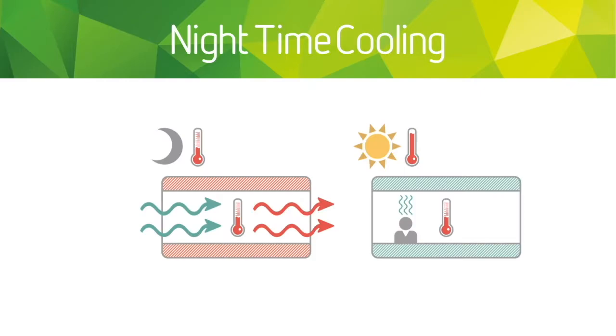Another type of cooling is called nighttime cooling. We are building more and more homes that are very lightweight, so this is not really that applicable. But if you can, try to have some form of exposed thermal mass in a space, and it can make quite a big difference. So in large office blocks, we've looked at providing night cooling. The same thing applies for homes.